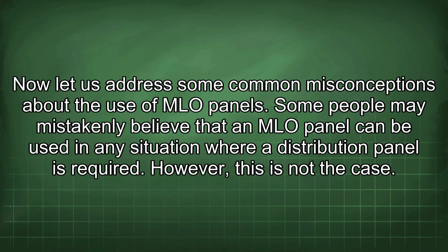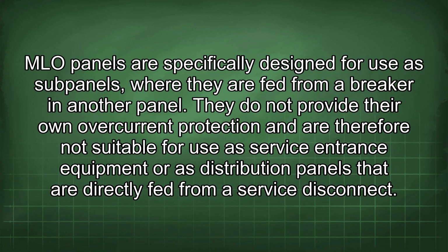Now let us address some common misconceptions about the use of MLO panels. Some people may mistakenly believe that an MLO panel can be used in any situation where a distribution panel is required. However, this is not the case. MLO panels are specifically designed for use as subpanels where they are fed from a breaker in another panel. They do not provide their own overcurrent protection and are therefore not suitable for use as service entrance equipment or as distribution panels that are directly fed from a service disconnect.